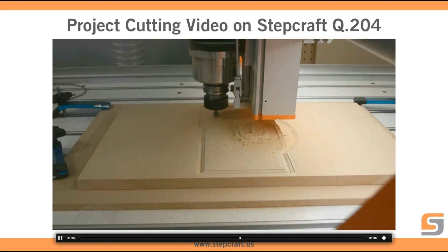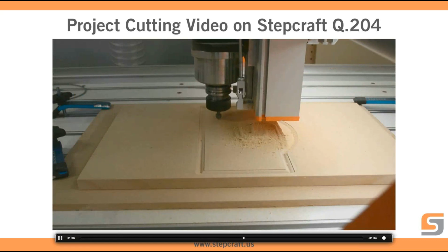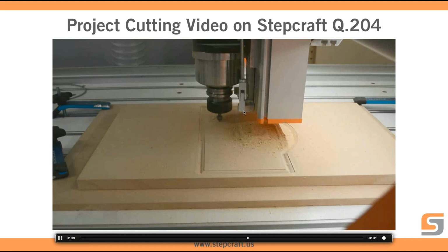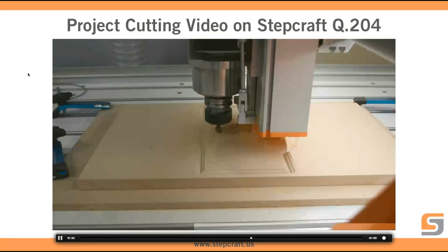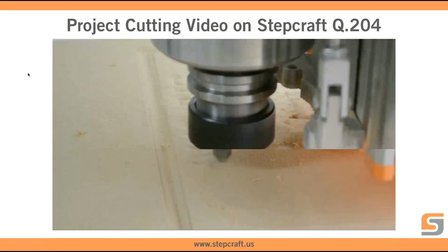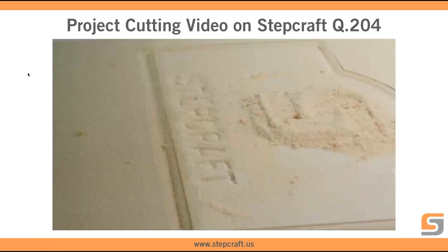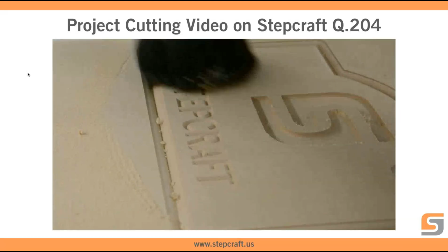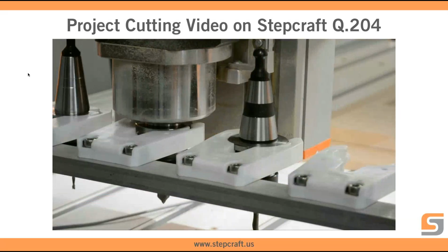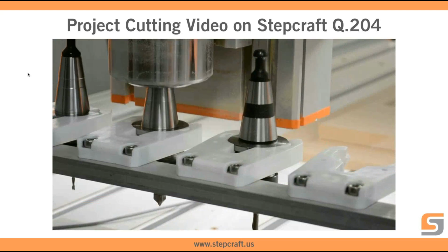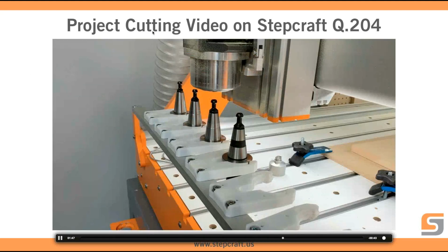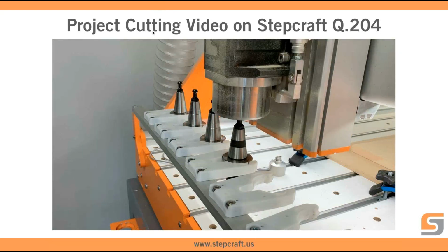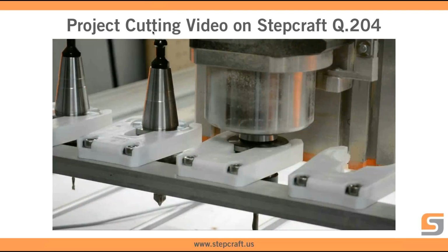You'll notice right here in the video, see this arm, you just saw it maybe come down. So one of the things that we designed here actually in the States, we have an automatic dust boot on this machine. We just took the dust boot itself off for the video. But what'll happen is there's a pneumatic cylinder there. So when the spindle turns off, when it's ready to do a tool change, it retracts upward so that the dust boot doesn't crash into the tool holders.